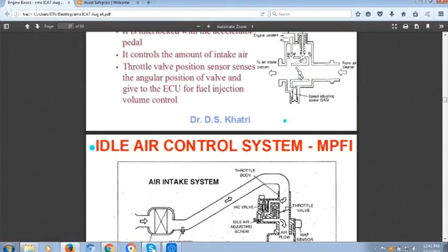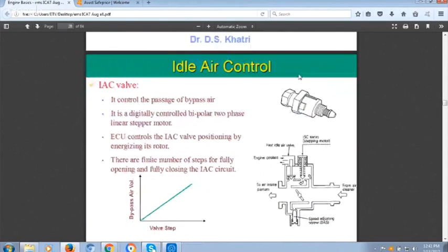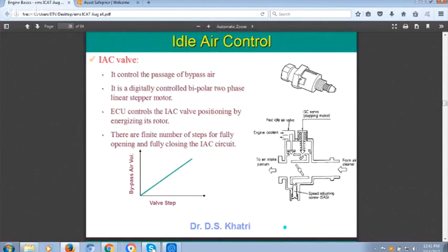Even what I am talking about, even ISC, the design of the ISC valve itself is very critical, because you have to control the flow from 1 liter per minute to 400 liters per minute, and controlling the airflow very precisely is a very challenging task. The sealing of that, the control of that, the controlling mechanism, when you design it, makes the difference.